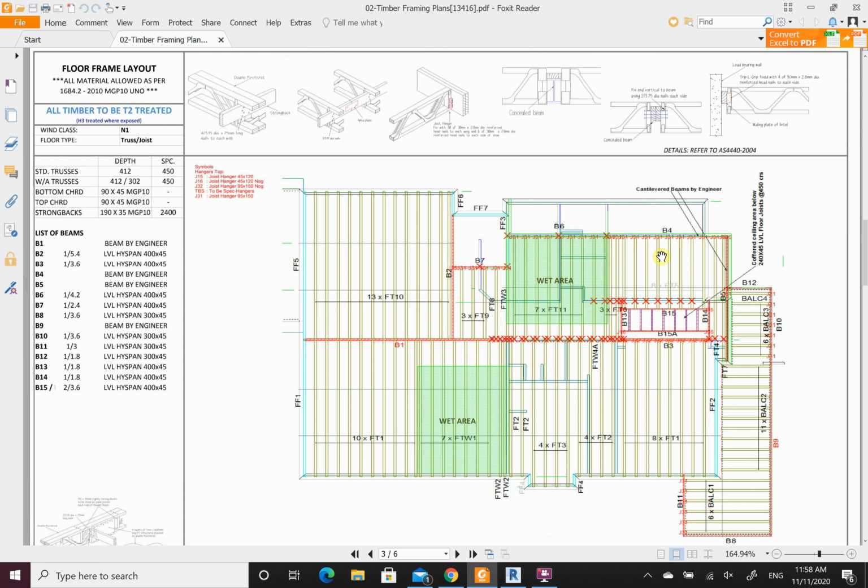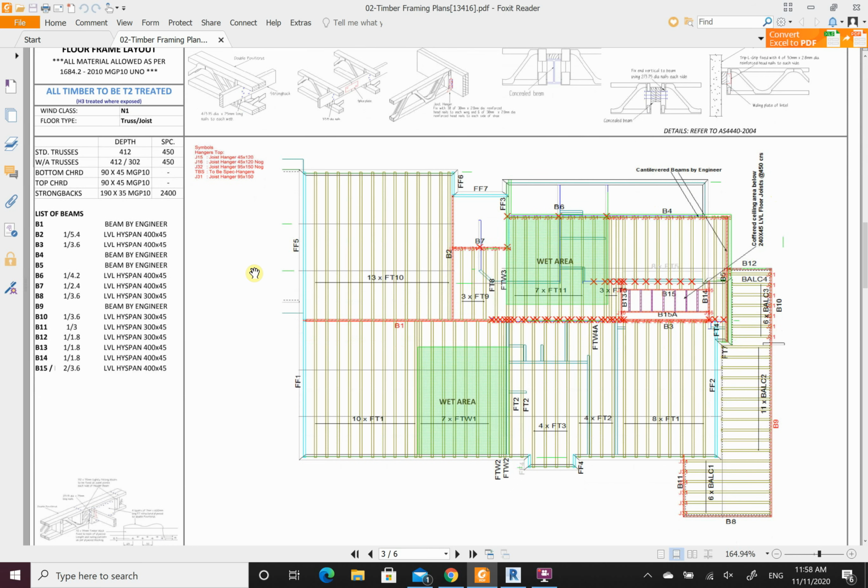Then you go through by first principles, software, or by your steel tables, and then you start designing the steel. It tells us what's happening, cantilever beams, a cathedral ceiling, so a couple of other details that you go through in analysis. But just again, so it's not the first time you see it next year or the year after, we're just doing a quick overview of it now. And then we've got some other beams at the front here, obviously for the balcony.